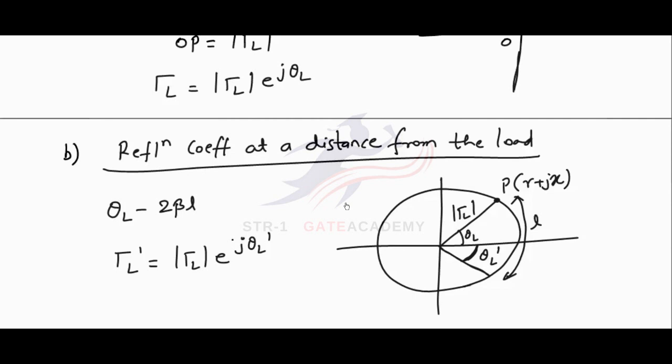So in this way we can find the reflection coefficient at a distance from the load. We are moving towards the generator and we have found the new reflection coefficient.